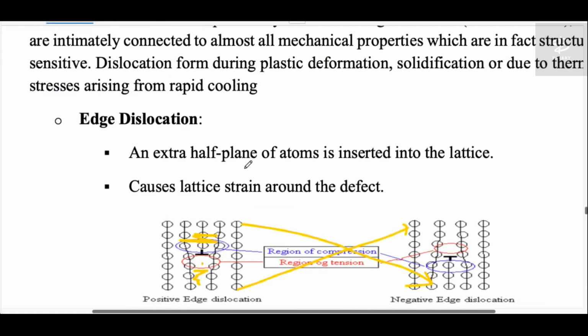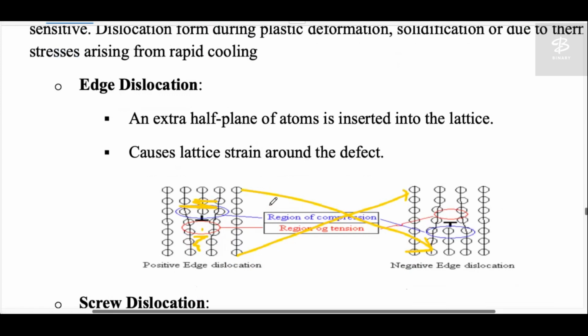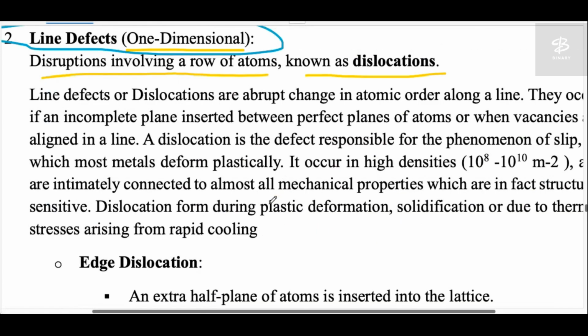You can think about it as a kind of small balls being kept in the form of lines. One of the lines is half completed and half of the line is missing, and that's why the nearby lines are compressed, to fill the space a little bit. That kind of empty space is known as edge dislocation or line defects. Okay, here's the definition.